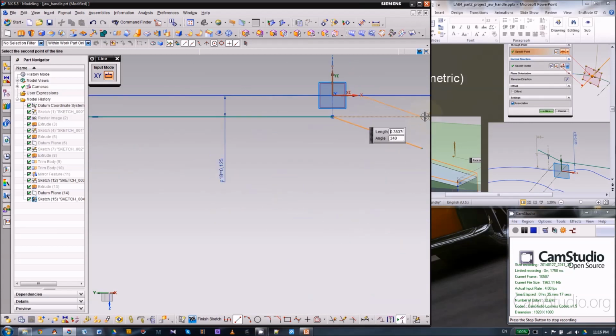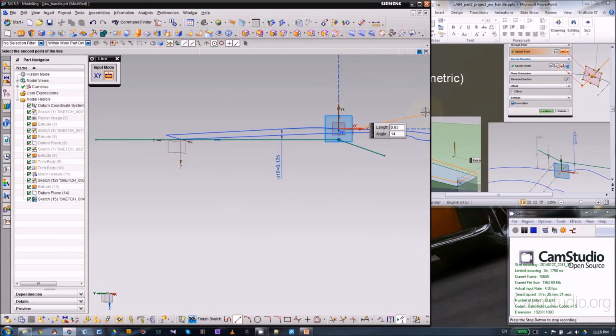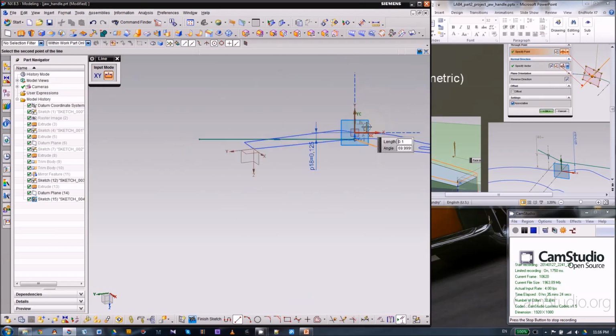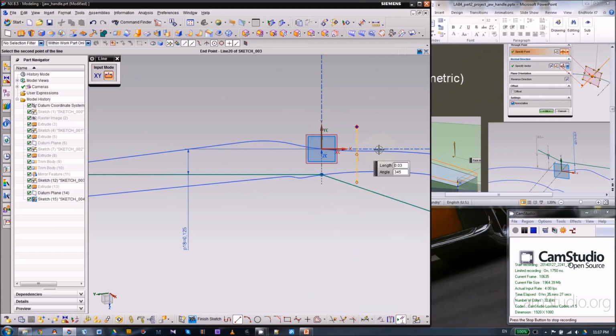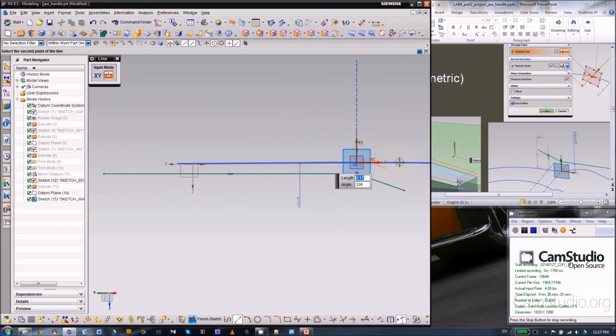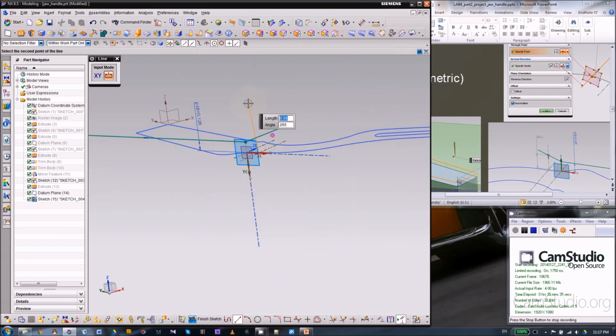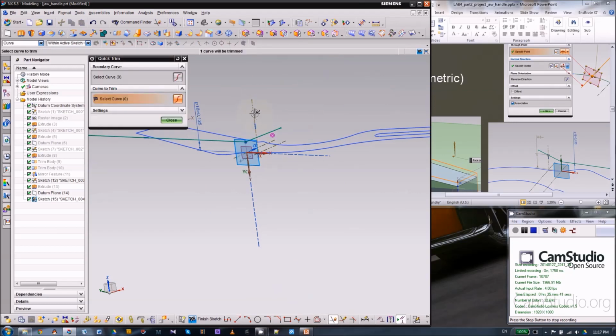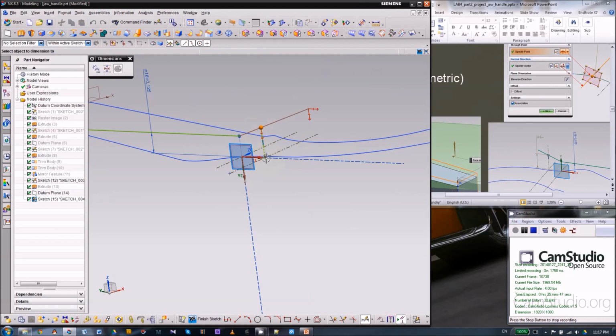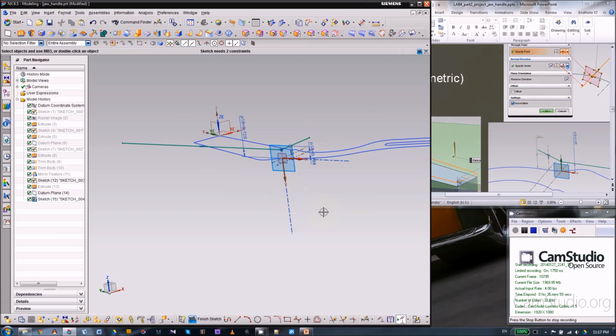Okay, and I'm going to rotate up. You can see I snap to the end point of this line here, but eventually it will project onto our sketch, which is here. So it's a vertical line here. I'm going to turn this to reference, trim this off, then give it a dimension, which is 3/16. All right, that will be enough for this sketch.